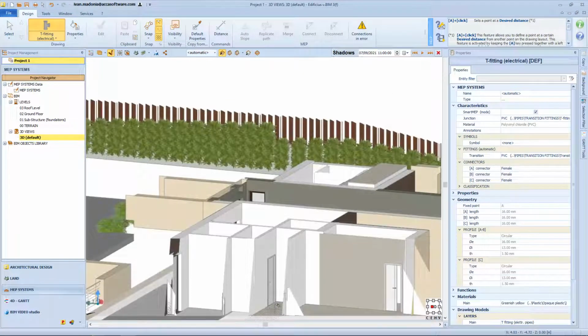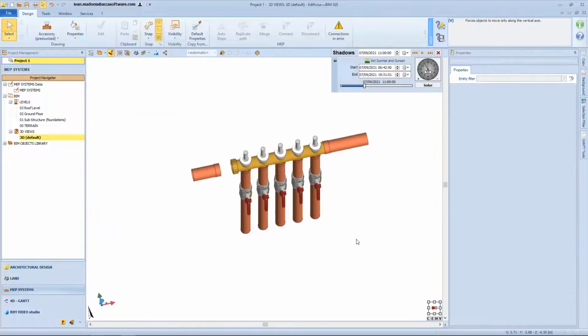Or, if you want to take as a reference a singular point of any other object, even if it does not belong to the plant environment, for example, the vertex of an envelope, you can use the blue snap. If we consider not a point but a line of an object in another environment, such as the edge of an envelope, the snap is still blue but takes the form of a line. The blue snap on an MEP connector object also appears when needing to connect multiple MEP entities to it.